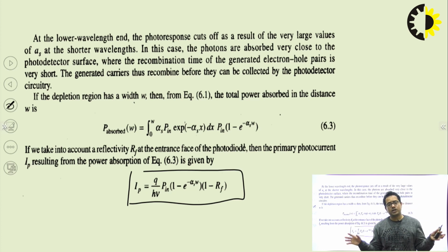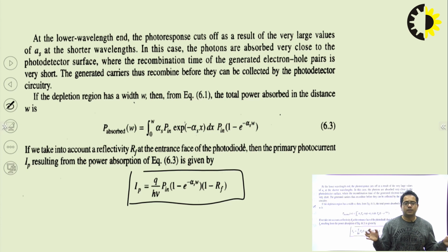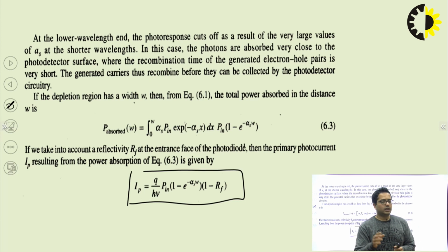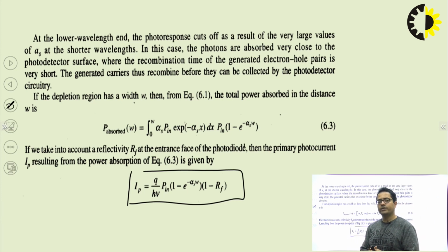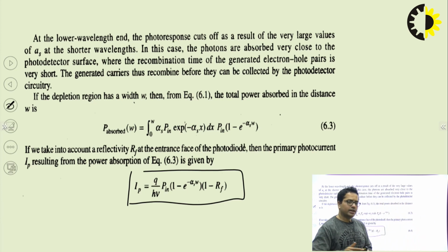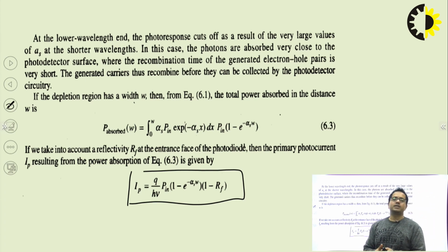If we sweep apart that electron hole pair by providing a bias opposite with respect to that charge carrier, like your p side has holes as the majority charge carrier, so connect that p side with the negative terminal of your battery, and the n side has electrons as the majority charge carrier, so connect the positive terminal with the n material. So you provide reverse bias to this junction, reverse bias this diode.